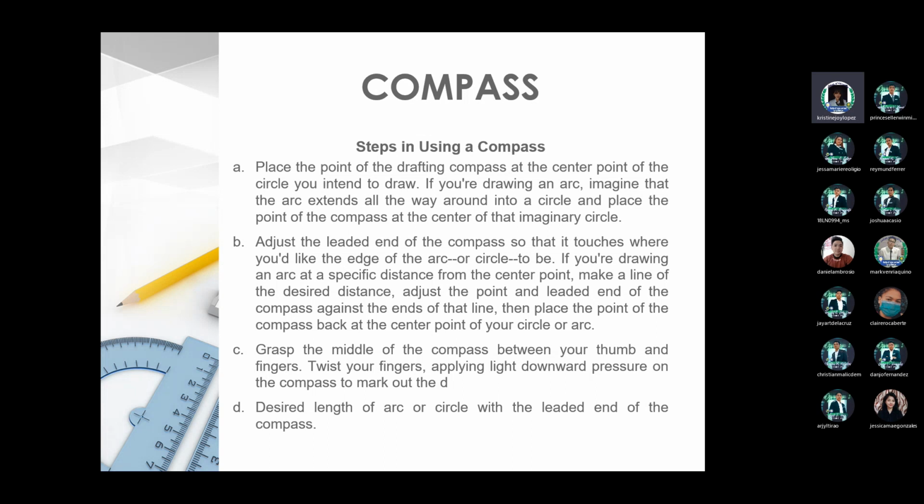Next is grab the middle of the compass between your thumb and finger. Squeeze your finger, applying light downward pressure on the compass to mark out the distance. And the last one is draw the desired length of arc or circle with the leaded end of the compass. So that is the step how to use a compass.